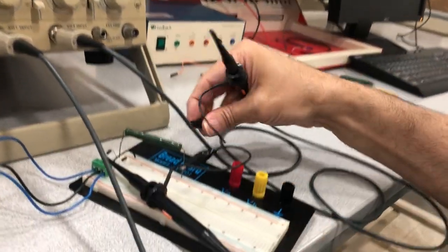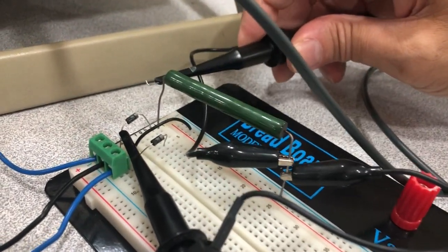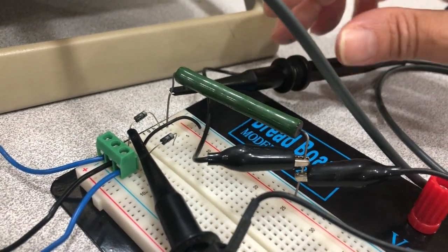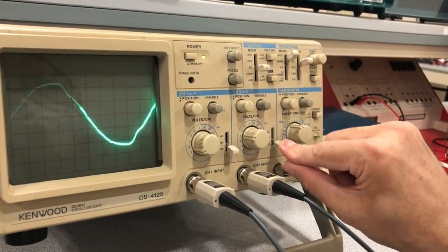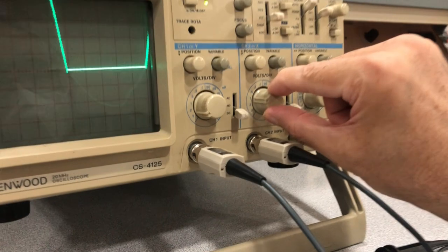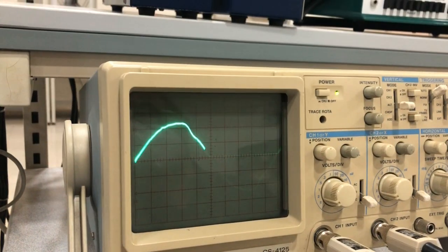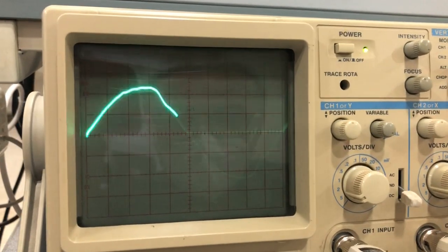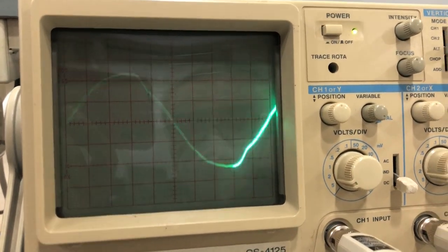Now our input signal is sinusoidal. We're going to connect our second channel, ground to ground, shield to ground, and we're going to watch the output after the diode, half rectified. But I have to turn on, now I go to DC, okay? We need to go to the same per division to be comparable to each other. Americans say comparable. Now there's flickering and magnification is turned off. I cannot do better than that.